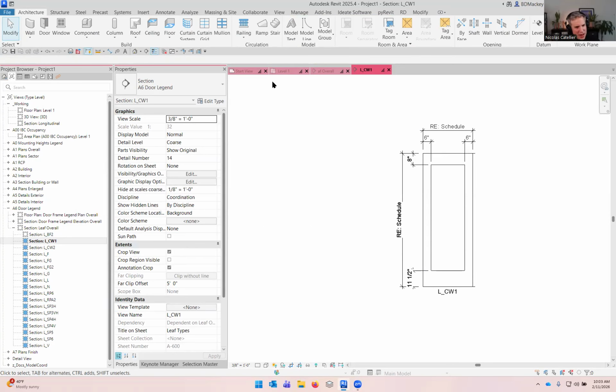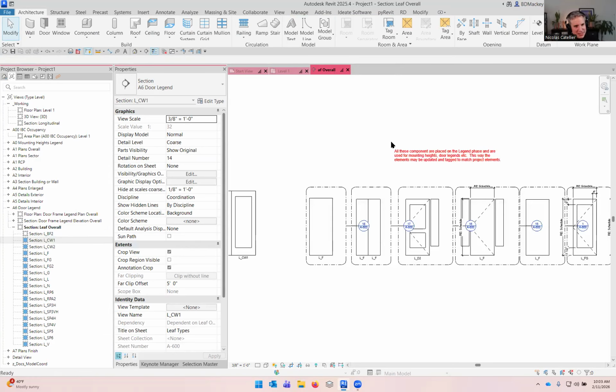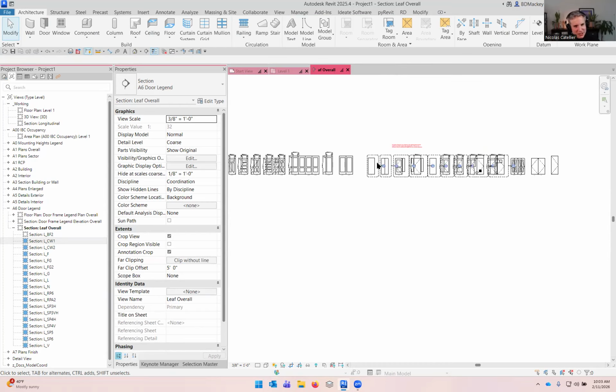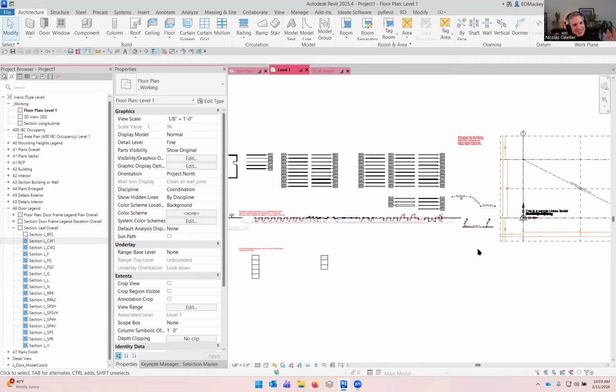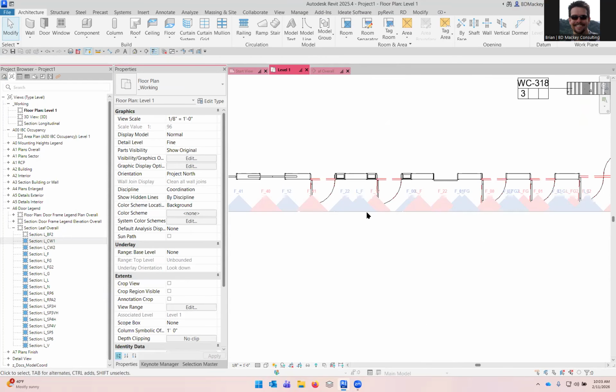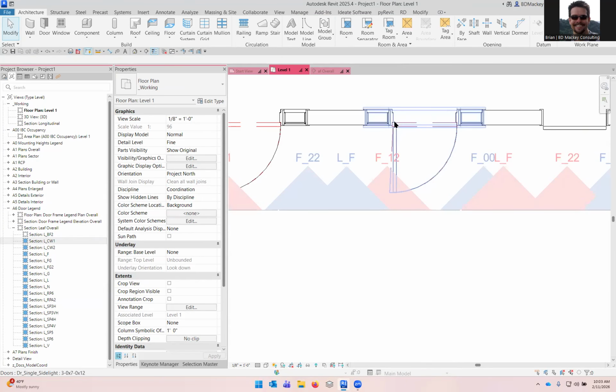So did you ever have issues with people not understanding the system and modeling stuff in the legend phase? That's something I would be really worried about, but maybe it's not a justified fear. Yeah, it absolutely can. I have partial problems with legend components because I can't do a legend component on my door leaf. If your legend components are work plane based, they will not let you choose which side you want to see, so I always see the edge of my doors.